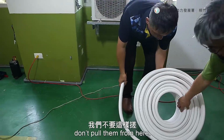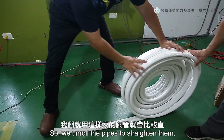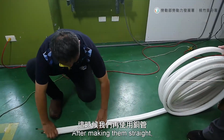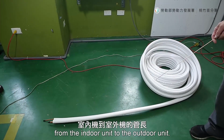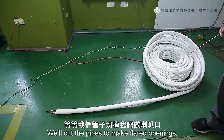When you do that, don't pull them from here. We want to keep the pipes straight, so we unroll the pipes to straighten them. They won't be straight if you simply pull them. After making them straight, measure the length of the pipes needed from the indoor unit to the outdoor unit. Now we'll unroll it. We'll cut the pipes to make the flare openings.